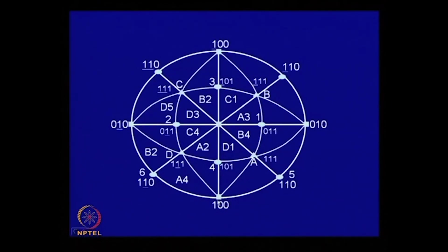They are the crystal axes, and they are axes of four-fold symmetry. So, therefore, it is represented with a square, and there are 4 planes of 1 1 1 type, which is shown here, 1 2 3 4. So, they are axes of three-fold symmetry, represented as a triangle, and these are the slip planes, and the slip directions are these. And what I have listed is, we have named these slip planes as A, B, C, D, and we have named the slip directions as 1, 2, 3, like this is 1, this is 2, this is 3.